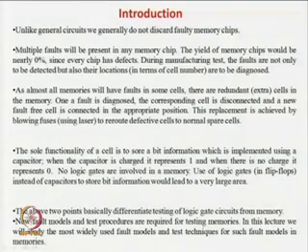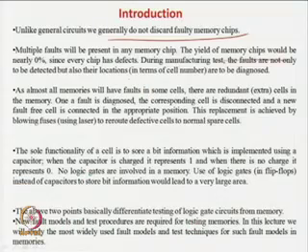Unlike general circuits, we do not discard any faulty memory chips. Why is that? If you start doing it, in the end you will find that only 1 or 2% of the chips can be sold in the market. So you cannot tolerate this. One thing is that you can make the memory layout in a bit sparse manner, so that the probability of faults is less. But then the chip area will be more, and it will not be profitable. So the yield of memory chips will be near about 0%, since every chip will almost have a defect.